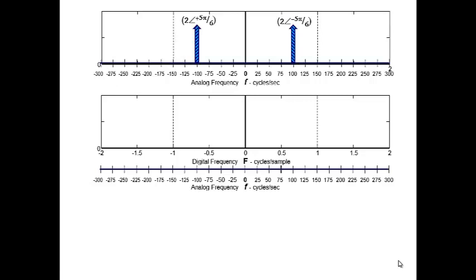Very important. All of sampling theory, other than Nyquist frequency, that's factoid number 2 that we really want you to come away from this sampling discussion knowing: when we sample a signal, its frequency spectrum becomes repeated copies of the original.